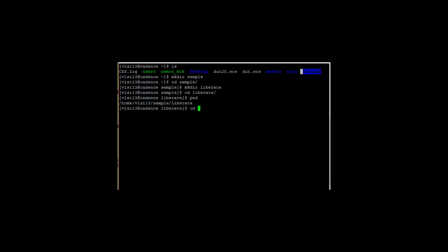I'll just get into the home directory and then the script directory to show you what is there in it. So here you could see there are two files. One is sptr to elc.pl, which is the Perl script which will remove the exclamatory symbols out of the netlist. The other one is the Tcl file that is meant to be used during our Liberate tool.